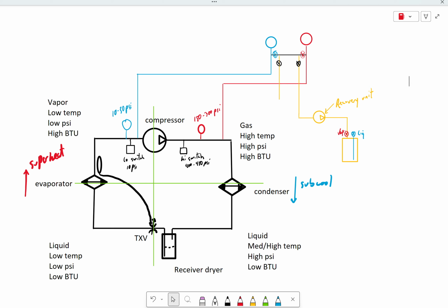So then your other question for yourself is, if I don't have a refrigerant identifier, how am I supposed to know? Thing is, if you don't know and if you can't trust the customer, assume it's contaminated. Put it in your junk tank. Now, it sucks when you're putting in refrigerant that is worth, realistically, what the customer is paying is probably close to $30+ a pound for it nowadays, and you're just going to throw that in the garbage. But it's better than cross-contaminating your own tank.